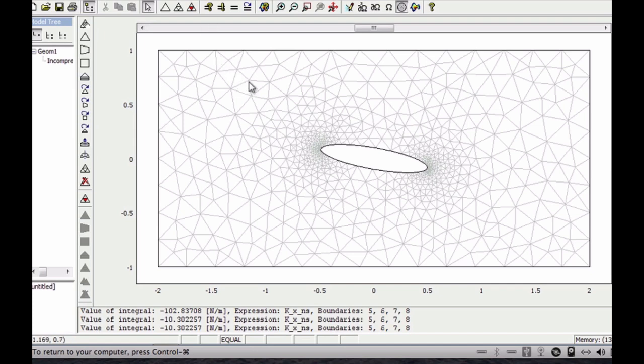We change that so that we have 3 equations for each of these nodes in the system, and in each of these nodes we solve algebraically for velocity in the x direction, velocity in the y direction, and the fluid pressure at that point. So 3 equations for each node, 3 variables, so we can solve them. We define some boundary conditions. The boundary conditions we had for this was that the velocity is coming in at 1 meter a second on the upstream far field boundary. The velocity along the top boundaries reach 1 meter a second. So in other words, it's just moving this flow down through the system. And we had a pressure boundary here of atmospheric pressure, 0 gauge pressure on the downstream system.